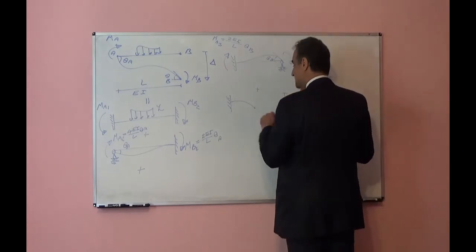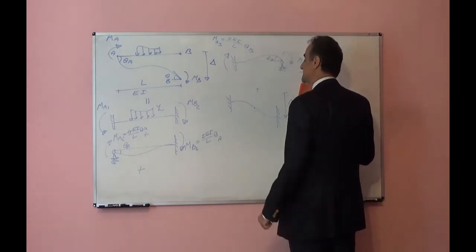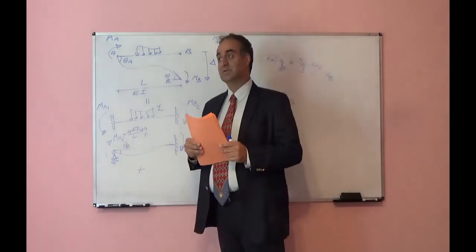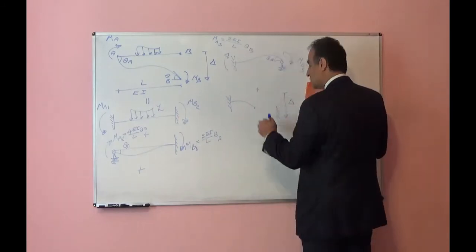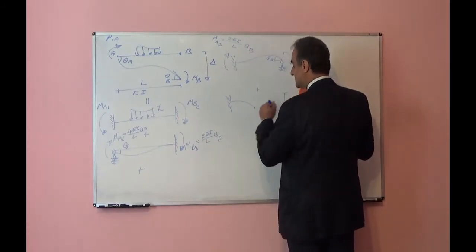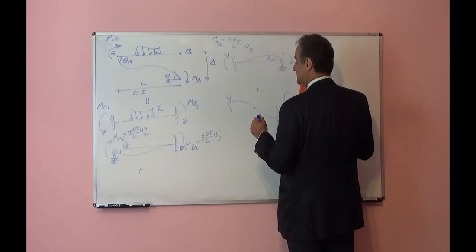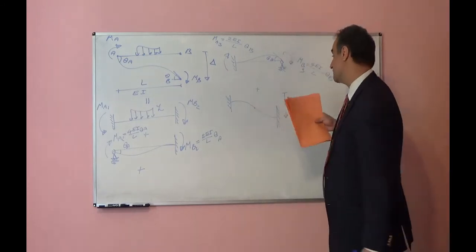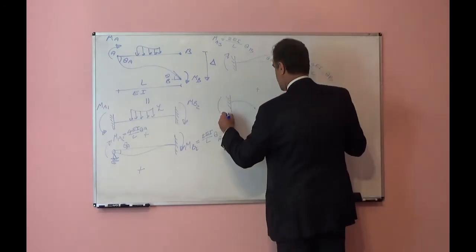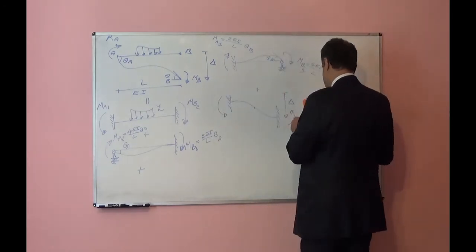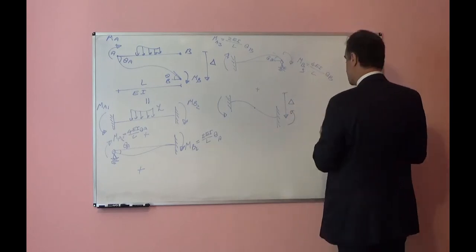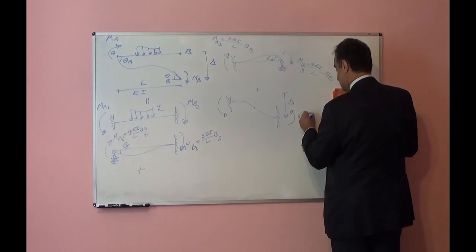So moment here is equal to 0 because curvature is 0 there; before that, and after that, the curvature direction will change. So at that point curvature is 0, that means internal moment at that point is equal to 0, and using the property of the inflection point, I find moment here because of the support settlement or lateral deflection. And if you remember, that was 6EI delta over L square.